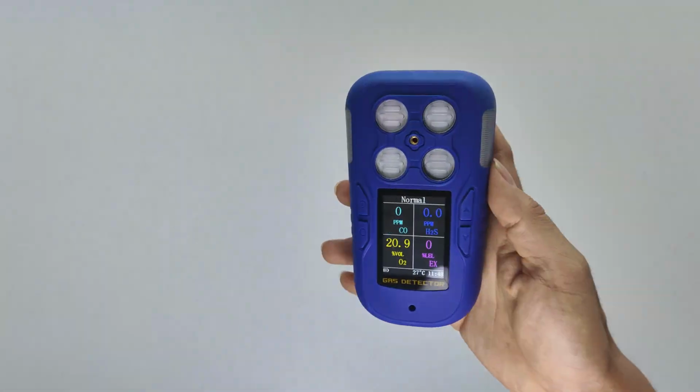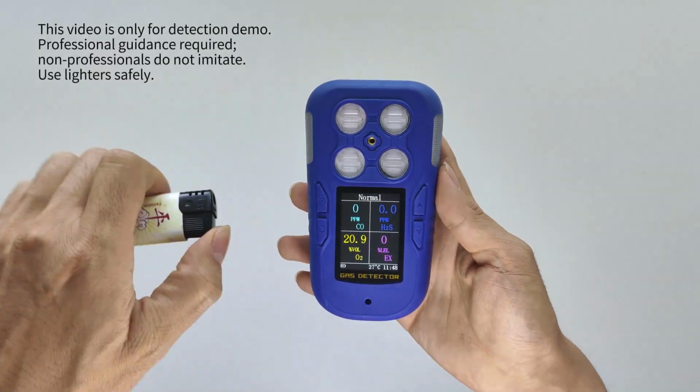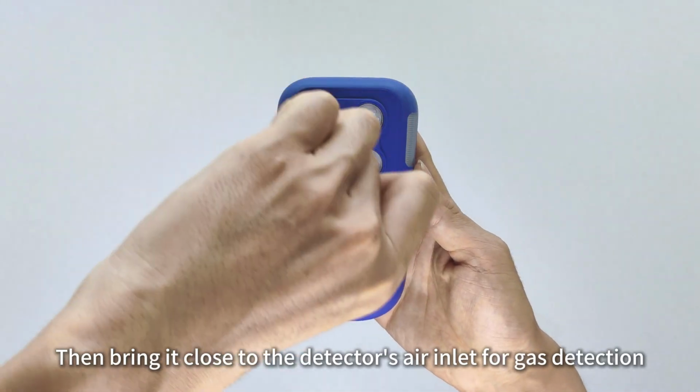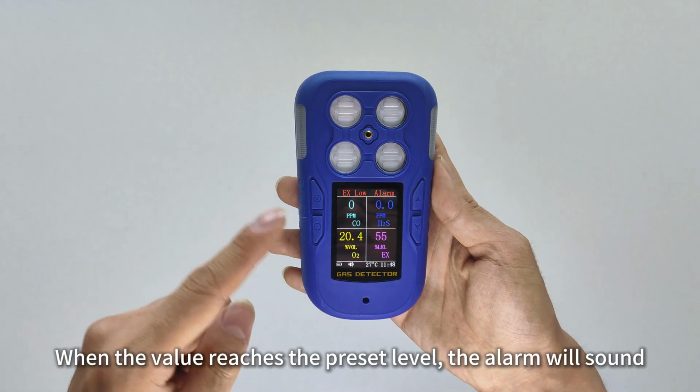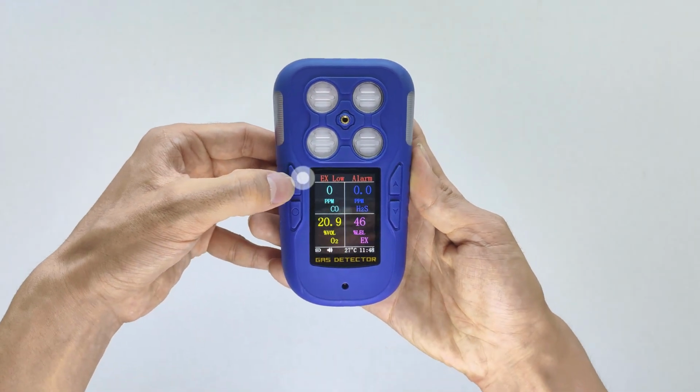Demonstration of alarm. Open a lighter, put out the flame, then bring it close to the detector's air inlet for gas detection. When the value reaches the preset level, the alarm will sound.